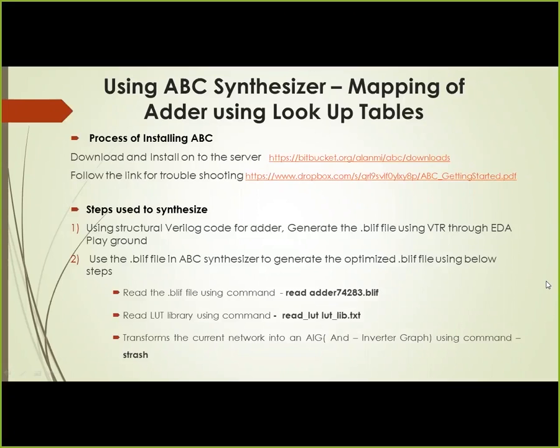The behavioral code has some disadvantages: the carry lookahead adder property is lost when we go for a behavioral Verilog model. So the main advantage of structural Verilog code is that the adder property is not lost.